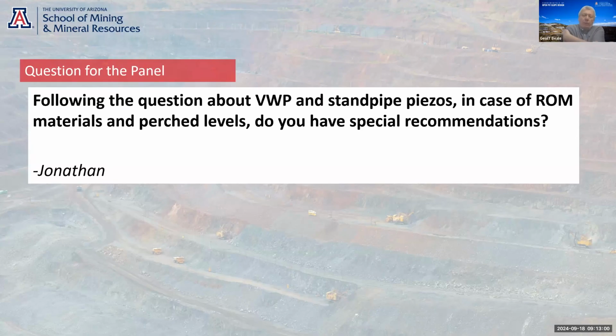But I think one of the things we've also been talking about is the LOP project is actually starting to think about this a little more, maybe triggered by the recent instabilities in the conventional leach pads in Canada and in Turkey. So I think there'll be some recommendations coming out from the LOP on piezometer installation in leach piles and dump leaches. But preconditioning the hole is a good way to go. Put in lost circulation material during or after drilling, and then put your VWPs in after that.